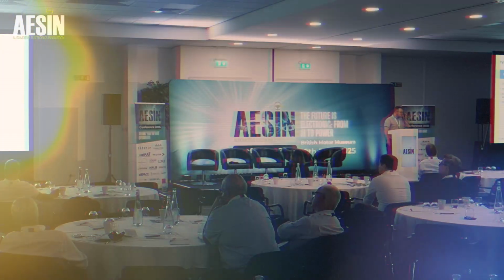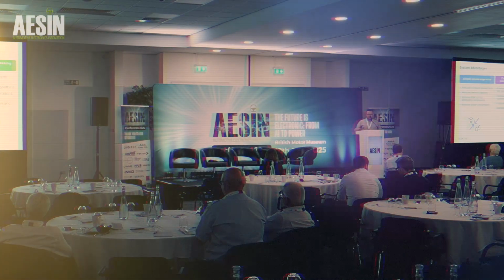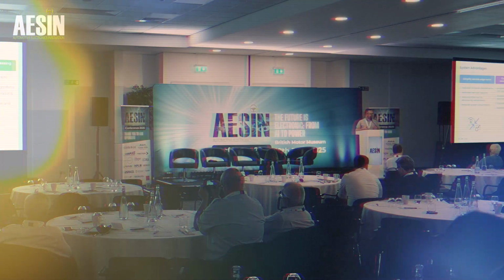So by simplifying the remote edge radar, we can reduce the compute requirements. We can use a cheaper and less power-hungry MCU there. It enables much more advanced algorithms and use cases. So not only can you deal with data from each radar individually and apply high-resolution direction of arrival techniques, for example, but you can also perform data fusion at the radar bridge level.